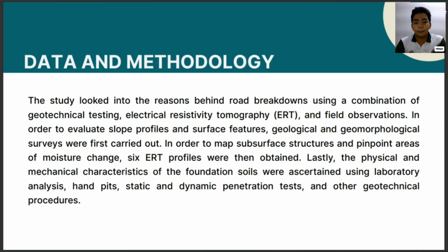In order to map subsurface structures and pinpoint areas of moisture change, 6 ERT profiles were then obtained. Lastly, the physical and mechanical characteristics of the foundation soils were ascertained using laboratory analysis, hand pits, static and dynamic penetration tests, and other geotechnical procedures.